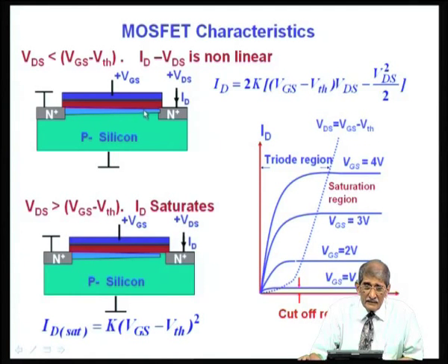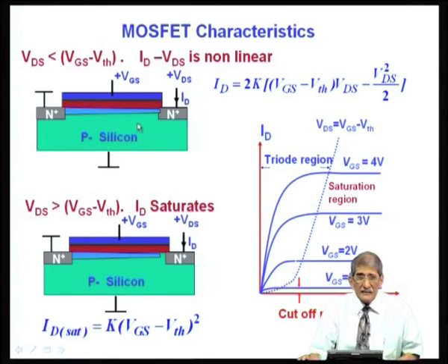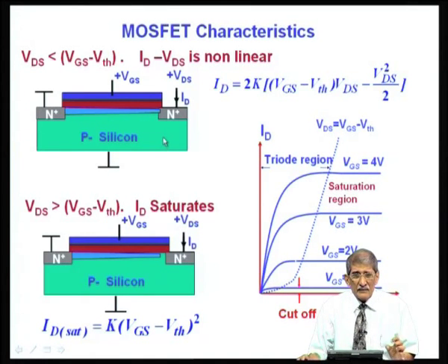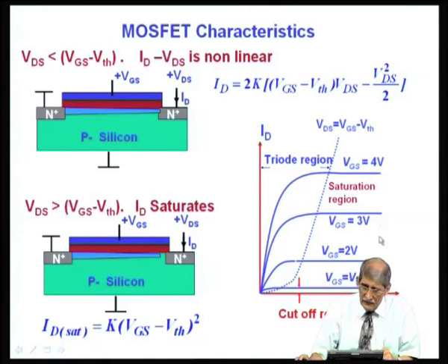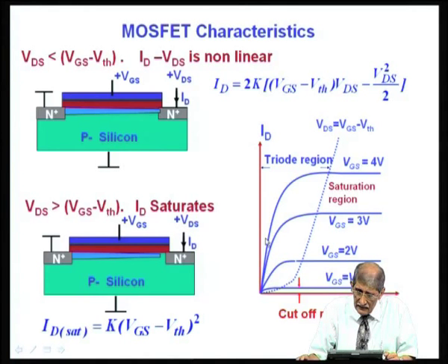because the area of cross section is decreasing, when the current begins to flow, the resistance increases. So, V is equal to I into R, but when you increase V, I increases, but R also increases. So, V by R is I. V increases, R also increases to some extent. So, I does not increase linearly. That is how in the VI characteristic, I does not increase linearly beyond a certain voltage.